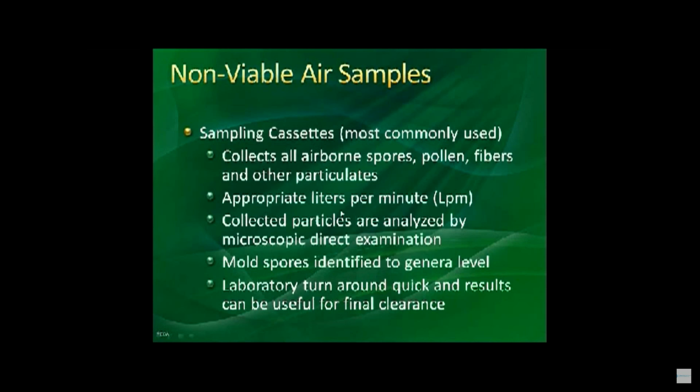The sampling cassettes all collect airborne spores. A lot of the labs will give pollen counts and fibers and other particulates. They'll tell you to use the device appropriately to the liters per minute recommended by the manufacturer. And any of the mold spores are identified to a genera level.